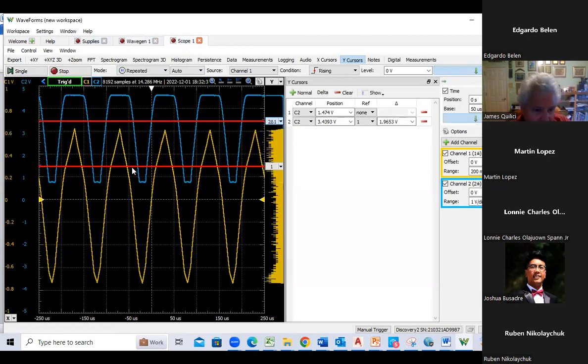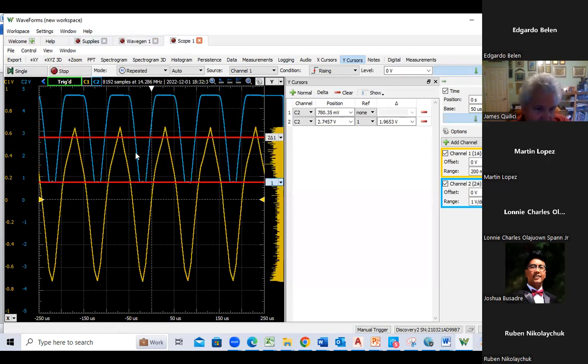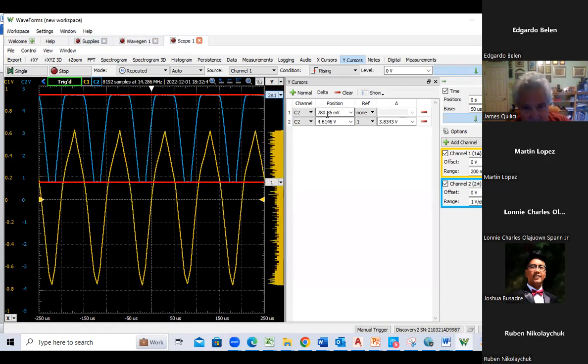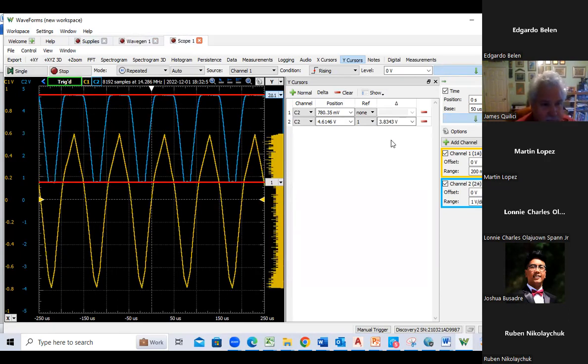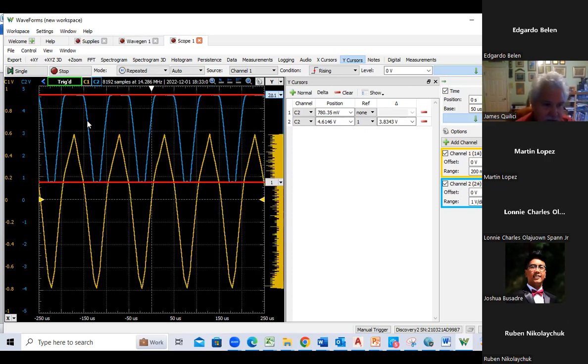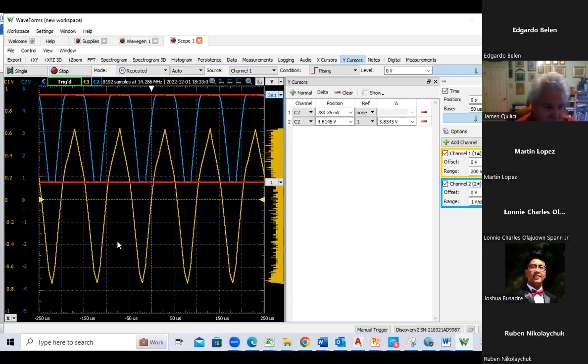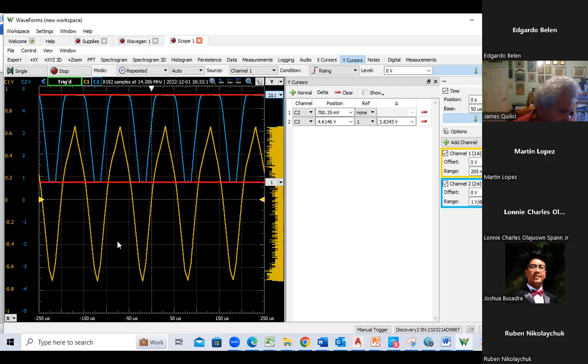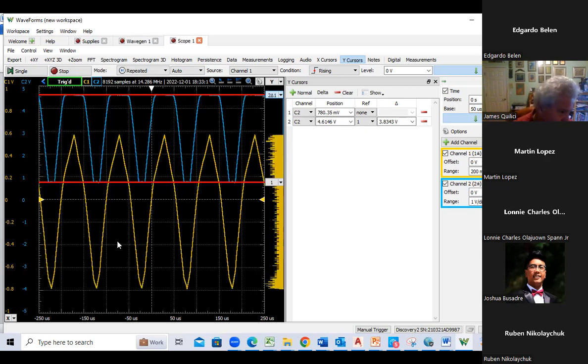Okay, so my dynamic range at my output is basically, I can go between 780 millivolts, which apparently is where my emitter is, and 4.6 volts at the top end. So I can get a delta of about 3.8 volts peak to peak. That's what we would call the dynamic range. And yeah, it's clipping harder. It's not necessarily symmetrical here. It's clipping harder on the positive end. But anyway, that's basically step 10, defining where your peak to peak is.